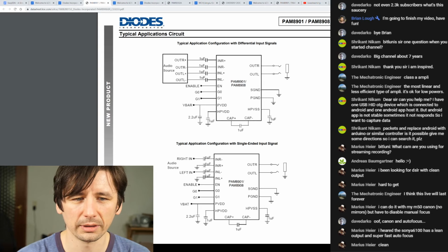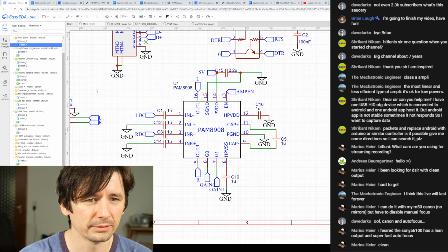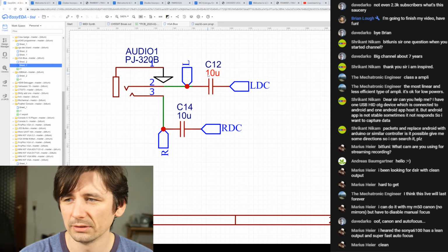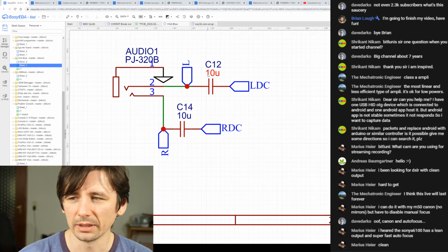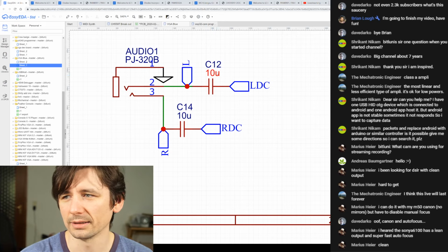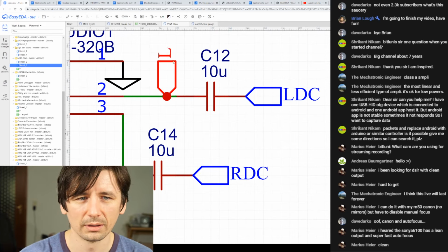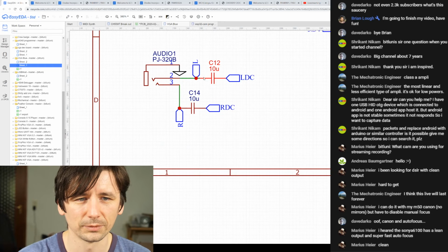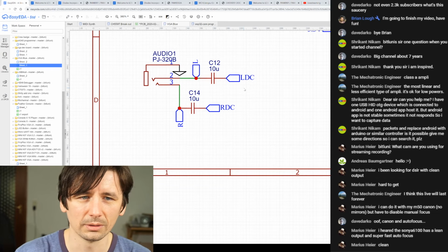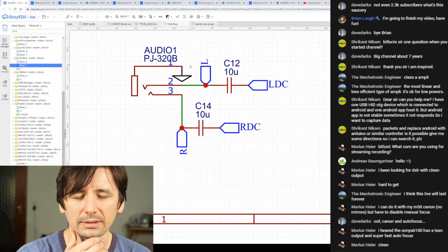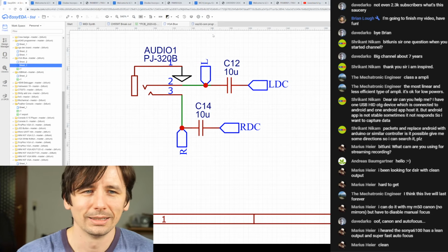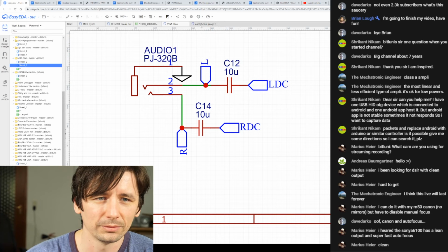The issue with the caps at the output that I had so far is that the lower the value here is, the more it acts like a high pass filter. I lose all the bass with filters like that. It will never be able to accurately give you a 20 hertz wave. It will always filter that, so you lose all the low end, and that's so crippling if you want good music, and it's a little bit disappointing. So I wanted to get rid of these.